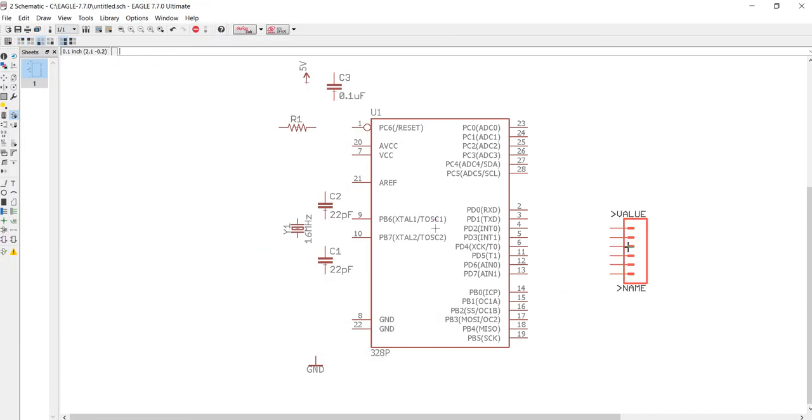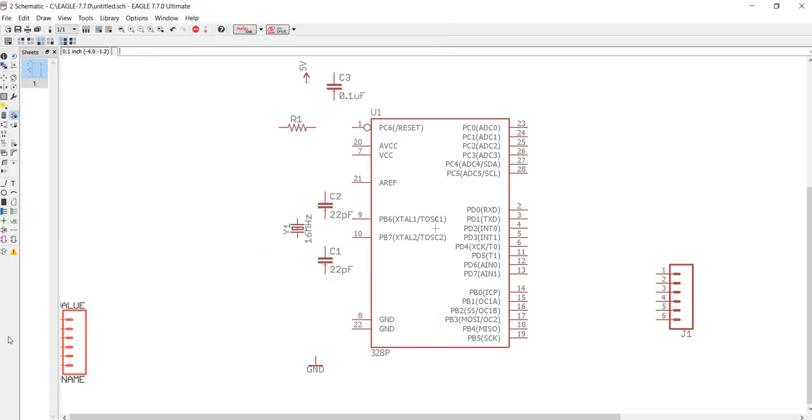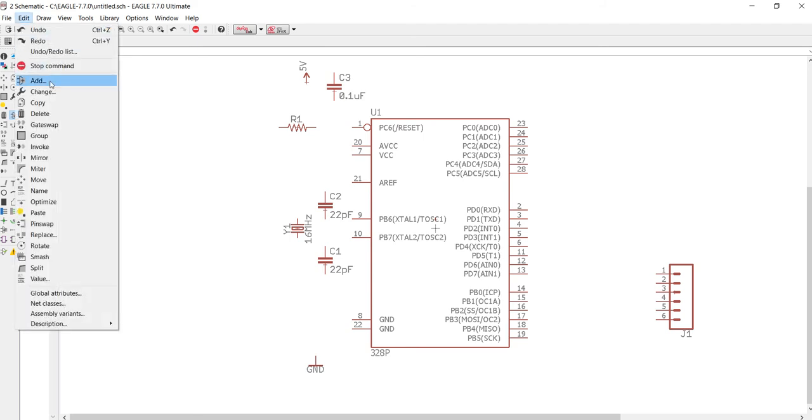The 6 is going to be for plugging in an FTDI cable, since we're doing a stripped down version of the Atmel 328P chip. Unlike the Uno, which has an FTDI chip built into the board, we're not going to add that, for simplicity's sake here today, because we just want to get through doing a basic schematic and then doing the board design.